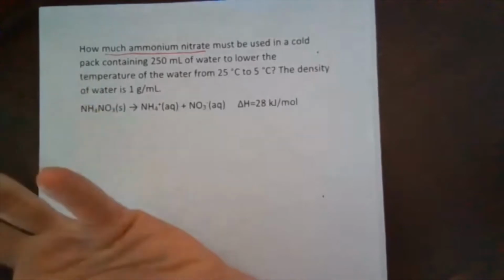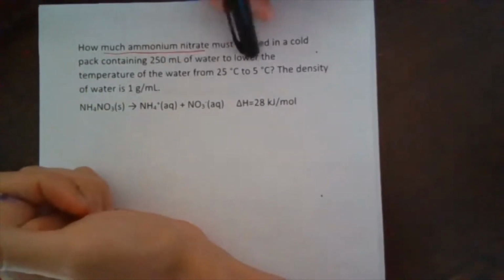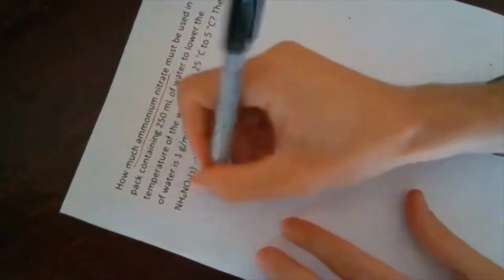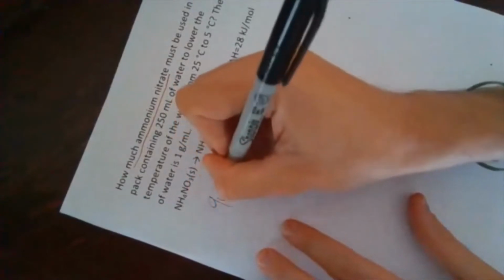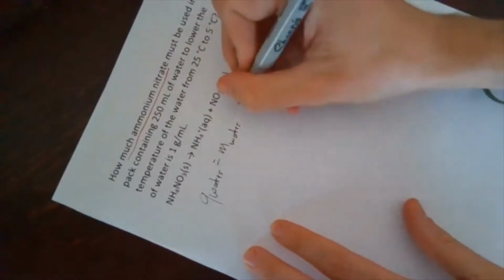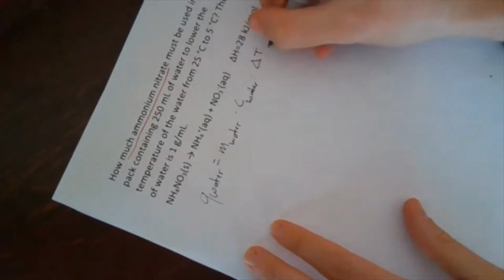So how much heat do we need then? It's going to be based around cooling off our water, we can see. So the question is basically, how much heat do I need to pull out of this water? And we know we're going to use our original equation for cooling off the water: m water, c of water, times delta T of the water.